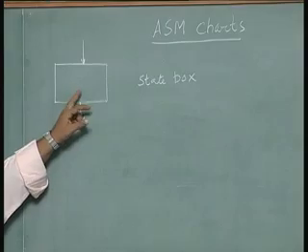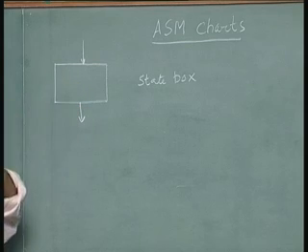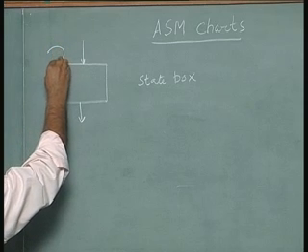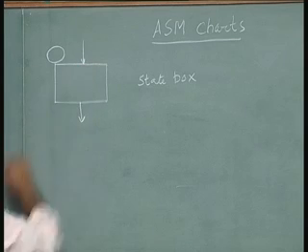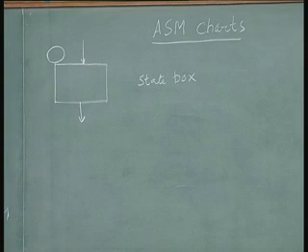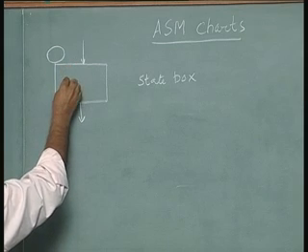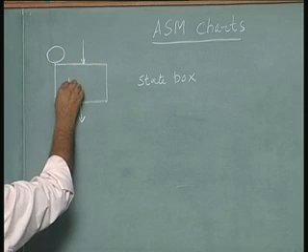So that is the same concept here, the state graph, the state box. The state box usually has a name associated with it. The name is given here on the left hand top corner outside the box, and inside the box you write the signals that will be generated as output in this state. So we will list, let us say, load, as an example.